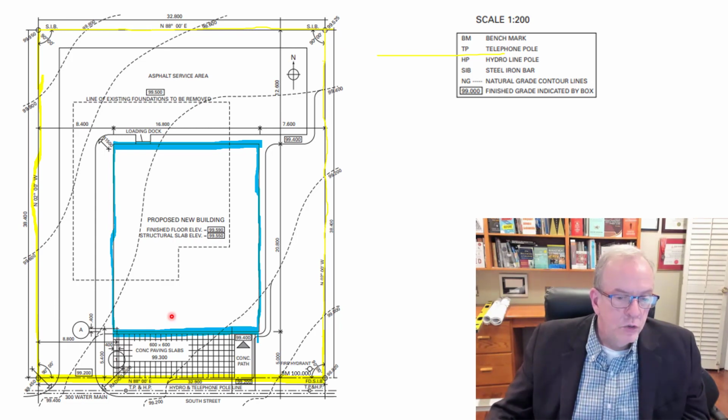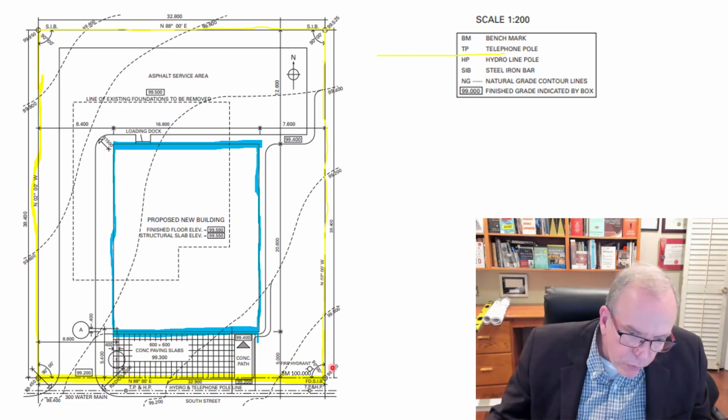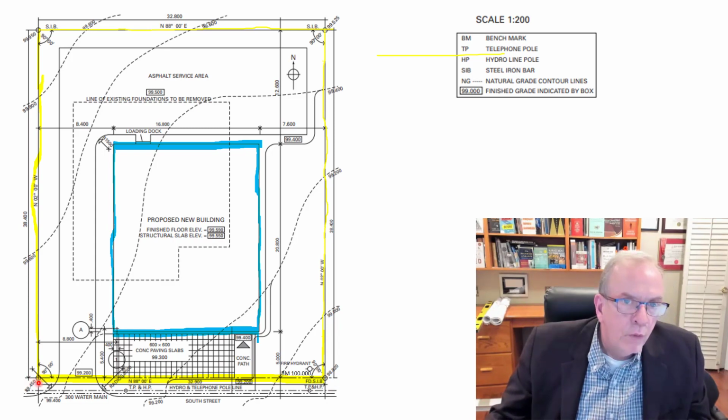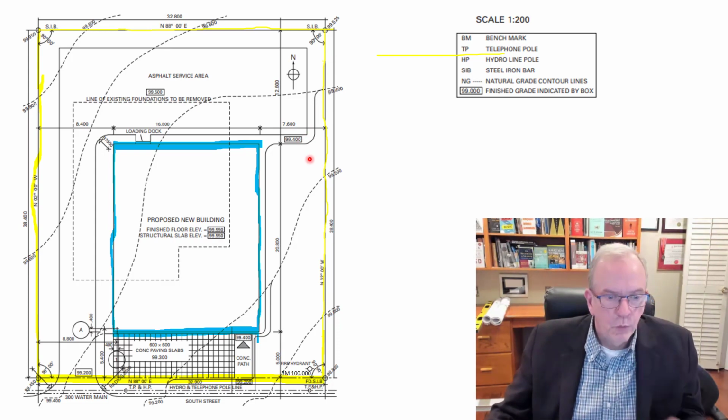So if I was to ask you what is the highest elevation on the corners, you could merely look around and you could see, okay, that's 99.950, that's 99.525, that's a little bit higher. You'd see down here that's 98.820 and 99.450. So you know that it's kind of sloping a little bit this way, right? And you see here it's 99.4, and so you got 99.4, 99.525, that it is indeed sloping a little bit that way, right? So it's giving you a little bit of that information.